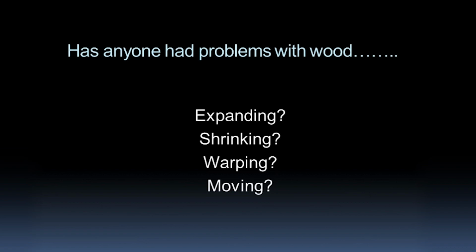He said that the permanent equipment will be up and running and the space will be conditioned. However, the permanent equipment does not have humidification capabilities, and he then says, we expect relative humidity lower than 25% during your installation time frame. The millwork should be designed to withstand the expected humidity levels in the building during service, which will typically be lower than 25% in the winter.